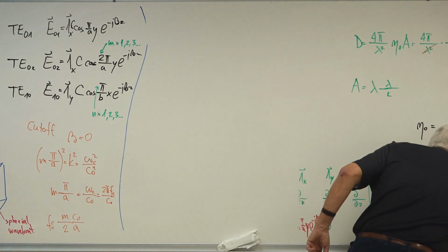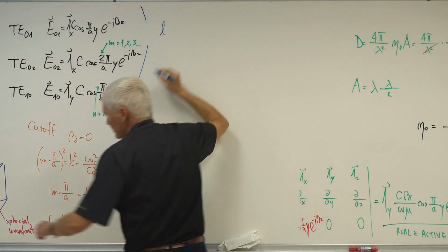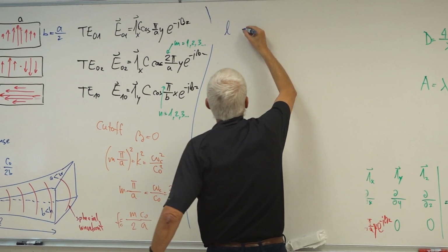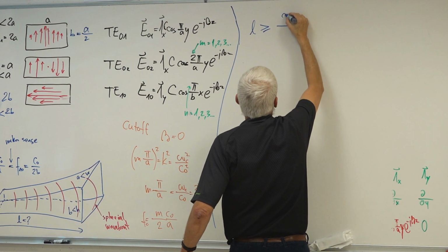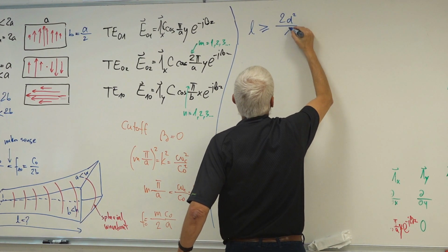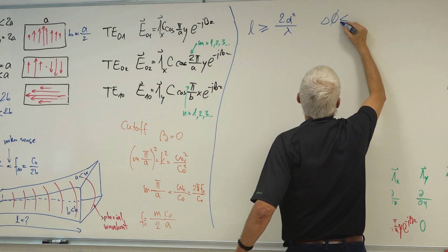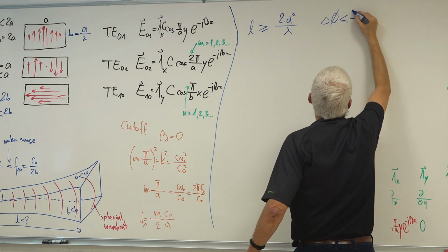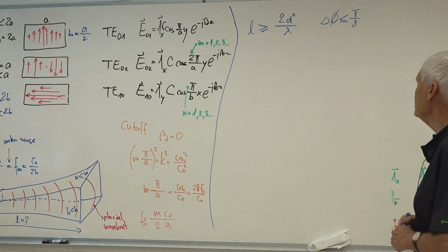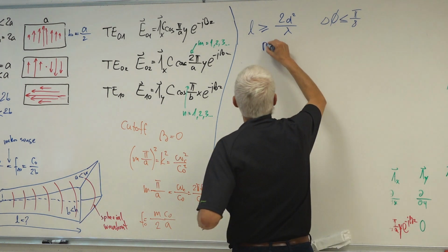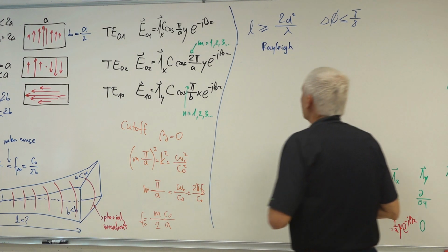If you remember from 2 weeks ago, this length of the horn, this L here, should be larger than or equal to 2d squared over lambda. This is for a phase error delta phi below or equal to p over 8. Okay? This was the Rayleigh condition, or Fraunhofer condition for the far field.